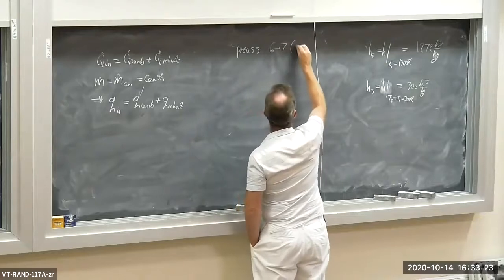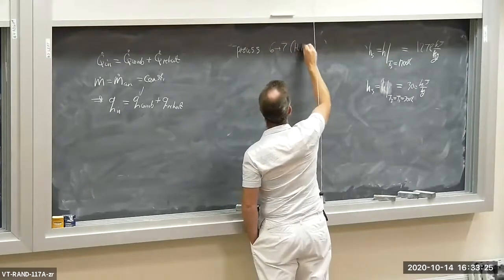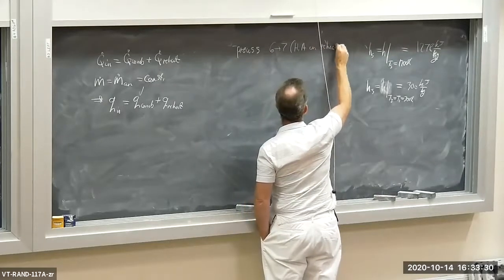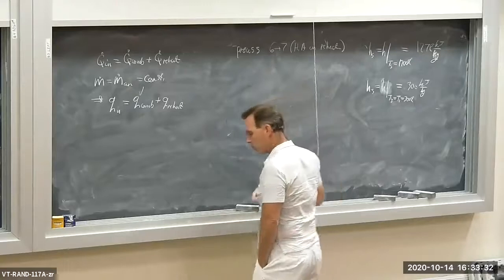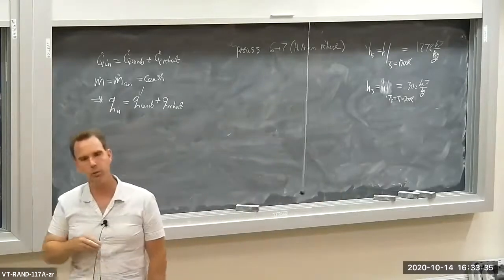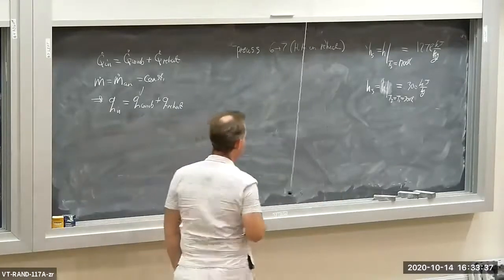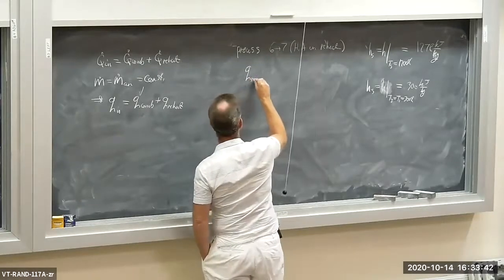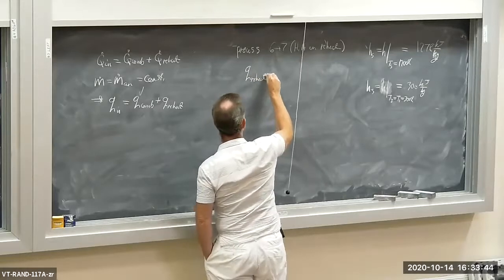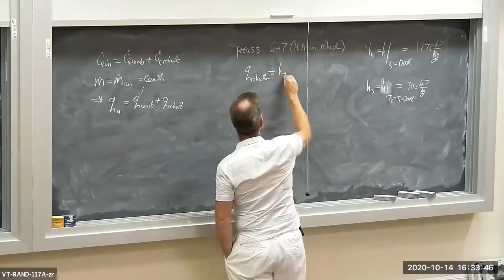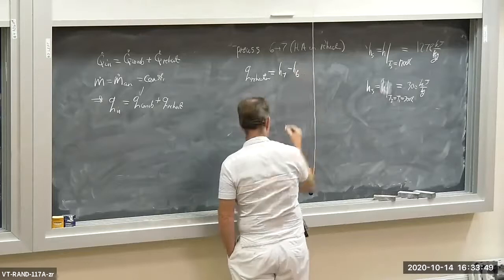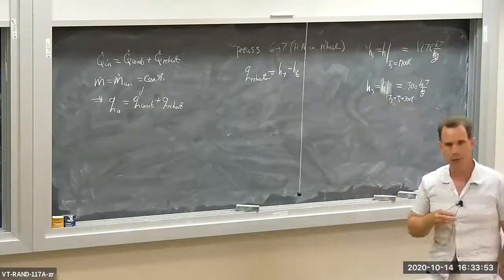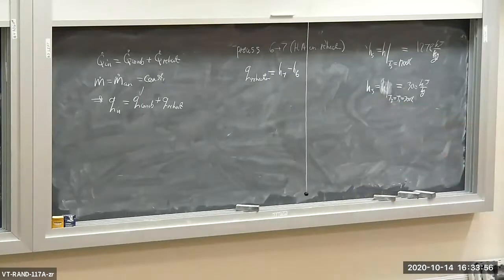So this is heat addition in the reheater. I apply an energy balance to the reheater. Steady state. No change in kinetic and potential energy. No work. And I get H7 minus H6, the specific heat added in kilojoule per kilogram of flow to the reheater.